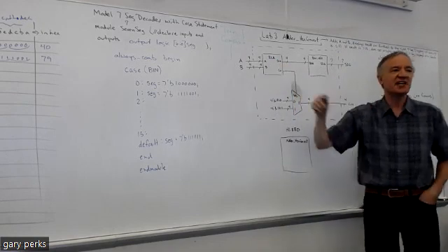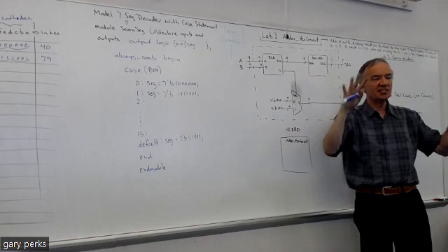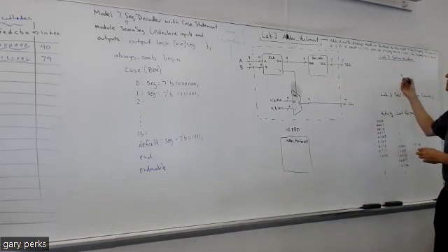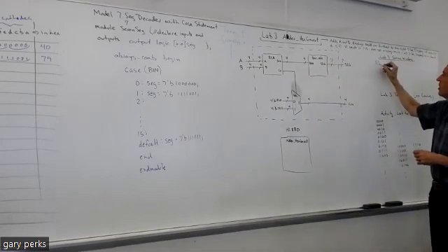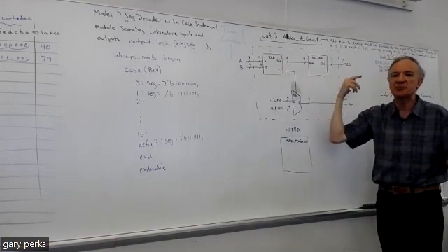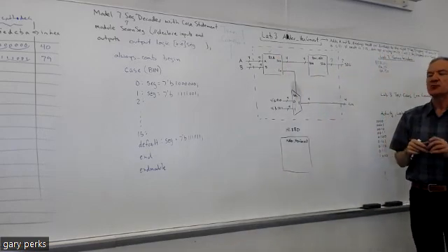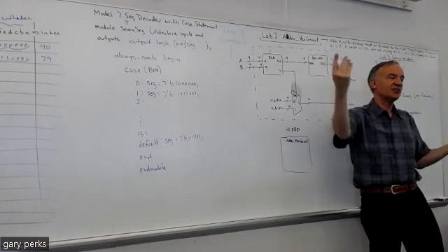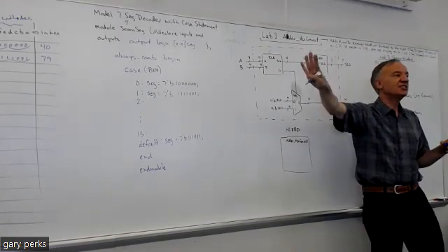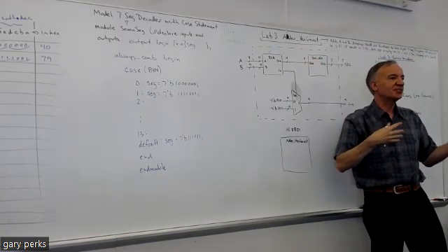So like I said last class, have a separate project for lab 3. Hopefully you've got separate projects for all the labs, and just bring over, in your design source window, the RCA design source, and also you'll need the full adder design source and the half adder design source. But you already have that, so all you have to do is bring that over from your previous projects. It's no added work. You don't have to sim it, because the assumption is that you already have a good simulation with your RCA, otherwise your lab 2 wouldn't have worked.